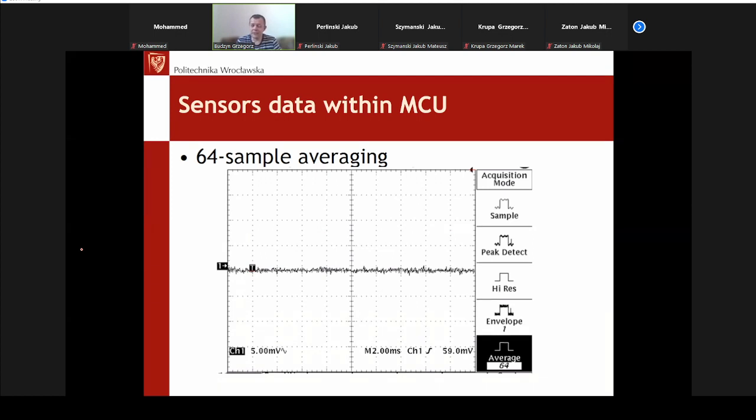because theoretically you can try to cheat. You can try to cheat the resolution, try to artificially increase the resolution by increasing the number of samples in the sample averaging, or the strength of the low-pass filter with the low-pass filtering.